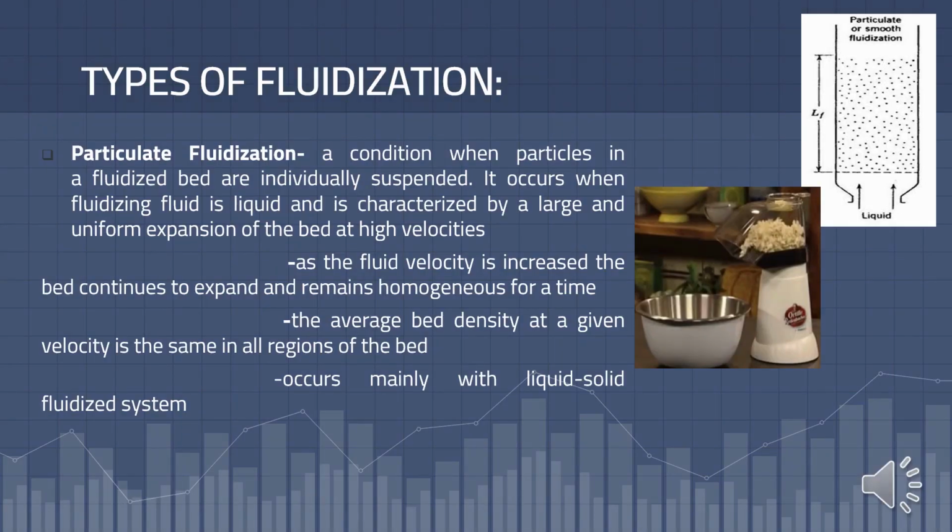It means after reaching this velocity, the particles will start to exhibit fluid-like properties. In a packed bed of small particles, when a fluid enters at sufficient velocity from the bottom and passes up through the particles, the particles are pushed upward and the bed expands and becomes fluidized.